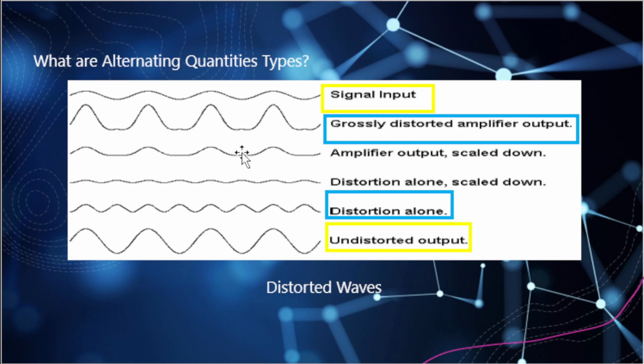And again, because let's say we're using an oscilloscope, the range that we select for our amplitude is also going to play a significant role. If I don't have this scaled per division correctly, I could be looking at amplified output like this and think maybe it's a good reproduced input signal, but it'd be hard pressed to tell if there was distortion on this lower peak.